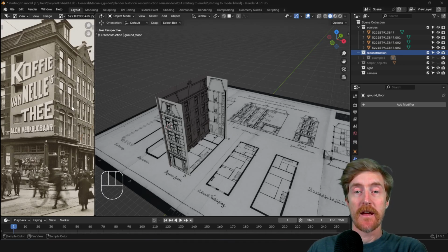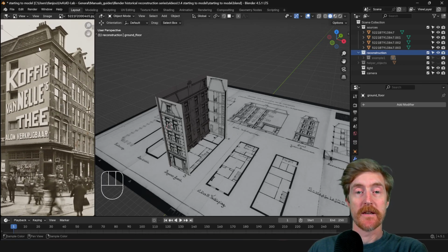the building. And in our case, we want to make a general subdivision between the roof, the middle part of the building, and the lower part of this building, because these are structurally distinct elements, so it makes sense to model them as separate objects. However, in our approach, we're going to start model them as one object and then separate them in three separate objects.